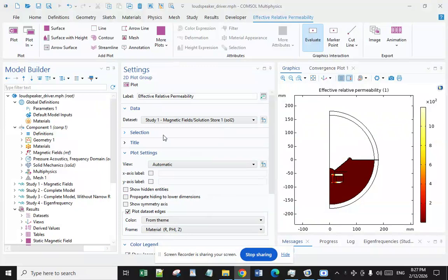An electromagnetic acoustic transducer is a transducer for non-contact acoustic wave generation and reception in conducting materials. Its effect is based on electromagnetic mechanisms which don't need direct coupling with the surface of the material. Due to this couplant-free feature, electromagnetic acoustic transducers are particularly useful in harsh, for example, hot, cold, clean, or dry environments.